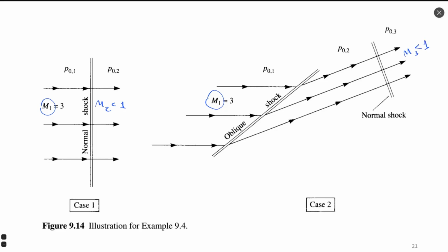The goal of flow passing through the shock wave is usually to efficiently decelerate the flow until subsonic velocity. It is done in such a way that flow can enter inside some duct, inside some piping of a jet engine, for example, and could be used as oxidizer and working fluid inside a working motor for a supersonic airplane or other types of supersonic devices.